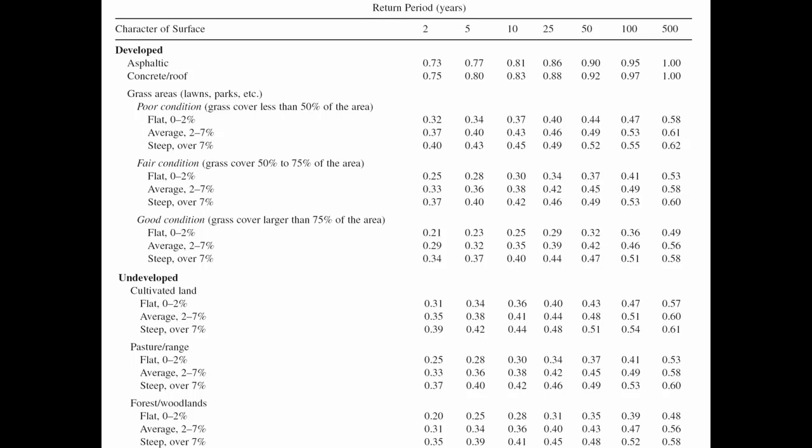But 18 hectares is housing. And again, that's a guess, and I'm just going to say that housing is partly grassy areas, but it's also partly roof area. And so if we did an average, a lot that's maybe half roof and half grass around the yard, then maybe a good middle ground would be 0.5 for that.